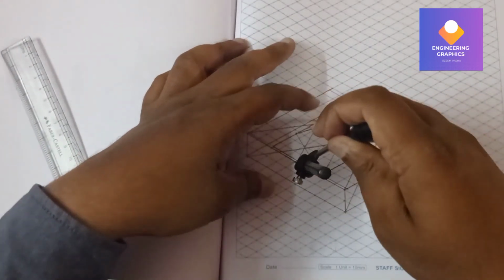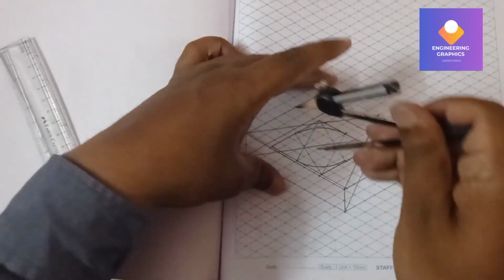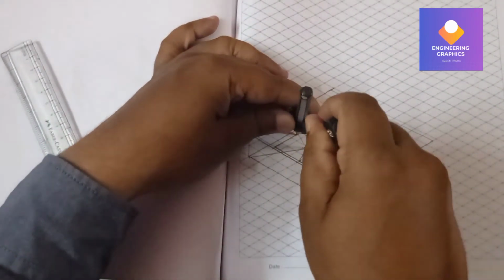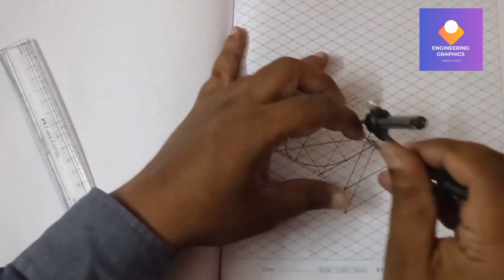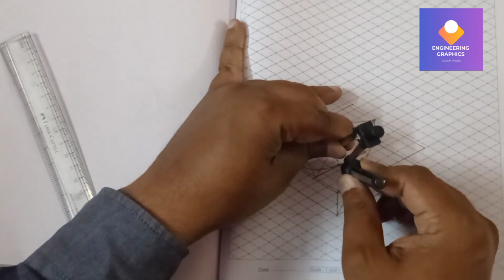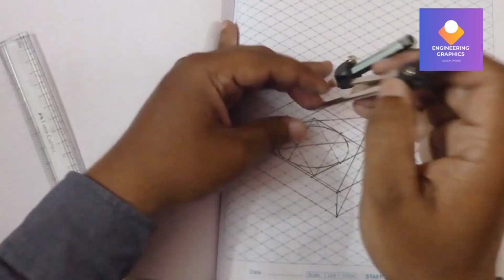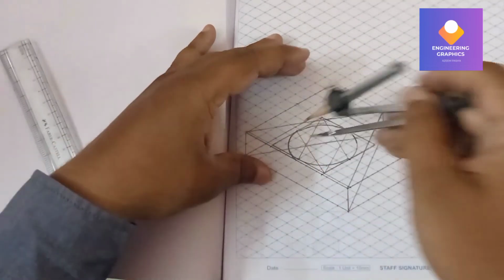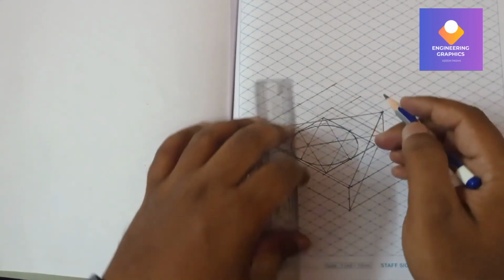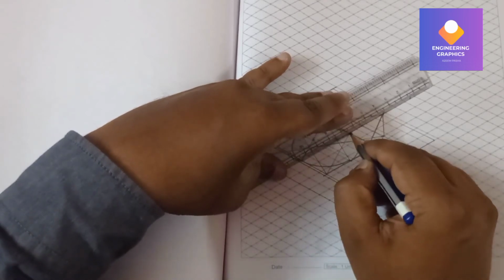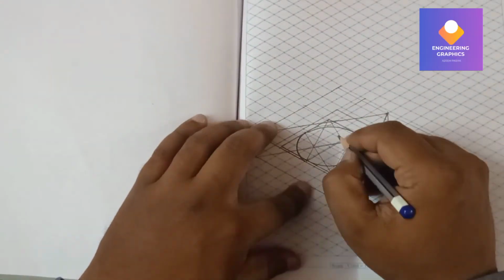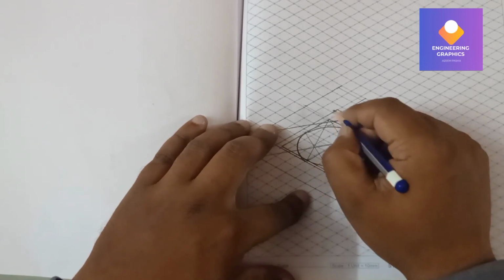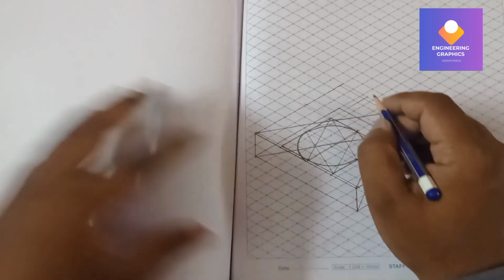Same way here also we should do it. Using that particular length, so measure it correctly to construct it. Now take a center point here. Just joining the middle points of the box, we get the center point. From the center point we should consider a height of 6 boxes. You can see the height is 60 mm. Consider a height of 60 mm and you can draw an axis here.